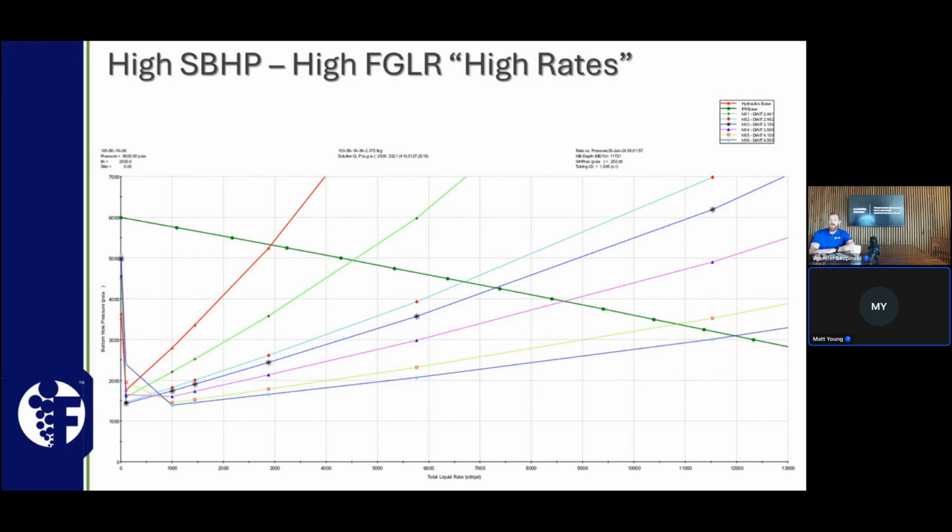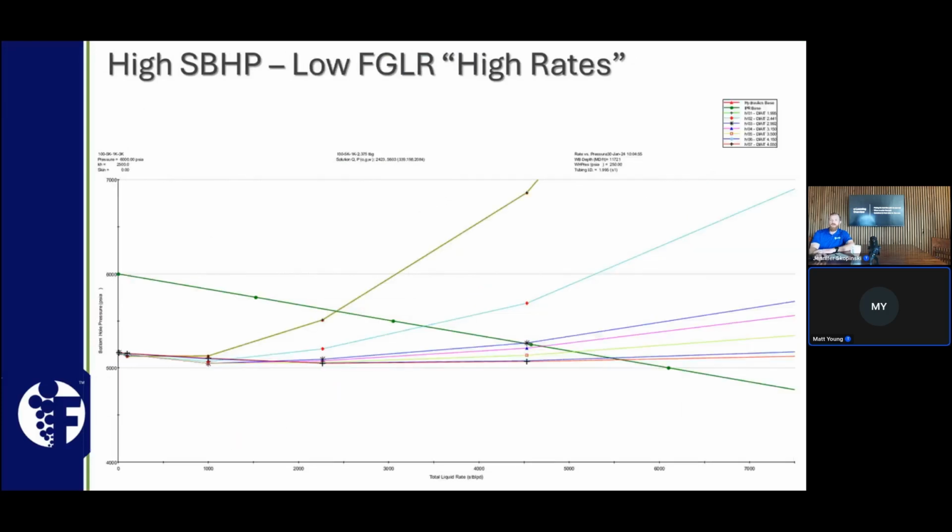So what we find is when we compare our hydraulic models for those different flow paths, our production incrementally increases as we increase our flow area, and our flowing bottom hole pressures decrease as we go through that. So you can see that progression as we work down.